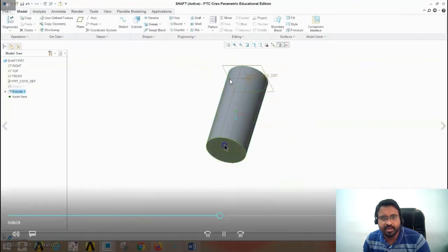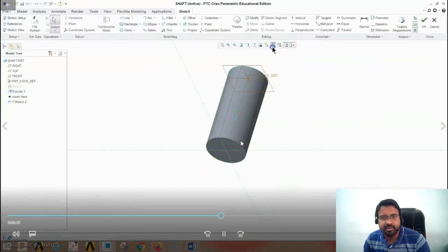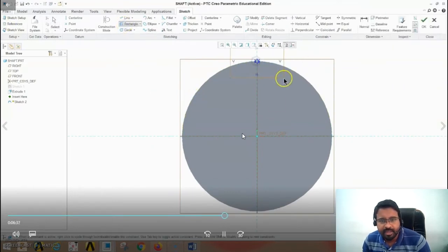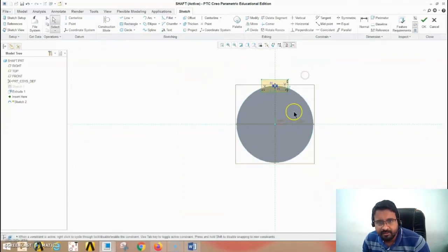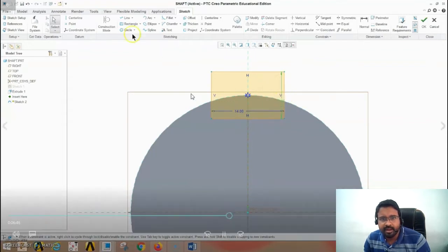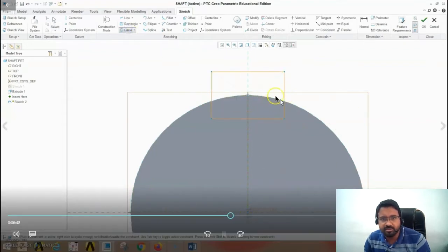So take the dimensions of the shaft, the length of the shaft, from the drawing, and now you can start drawing the keyway. As we did in the flange, here also we can create the rectangle with center reference and then cut away the extended portions using the trim option. Here you are drawing the circle, so that line is created over here. This line and all this rectangular line will form a boundary to form an area, so we can trim all the other portions.